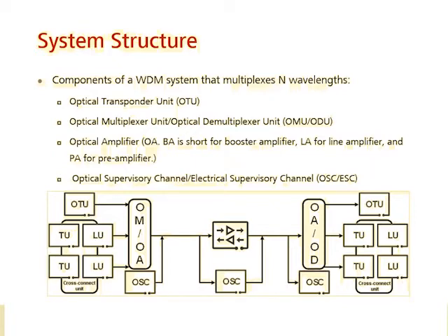For example, if for the first OTU board the WDM side interface is broken, what should we do for troubleshooting? The only thing we can do is go to the equipment side and use a new board to replace the broken board. Then your service will be restored, right? But we don't have any solution to fix your service otherwise, so we thought it's pretty dangerous.